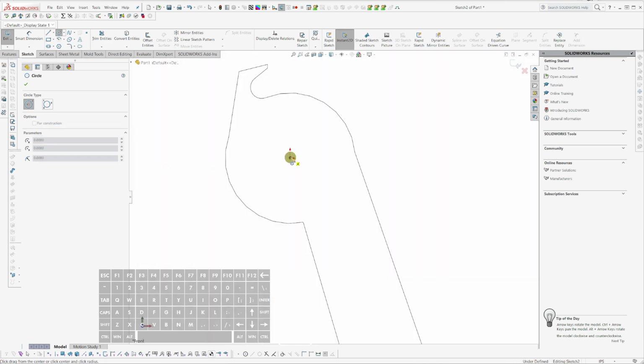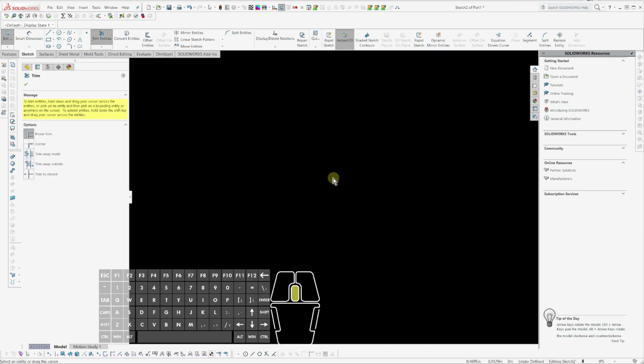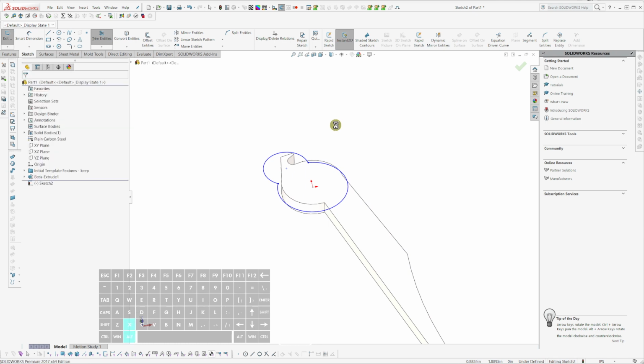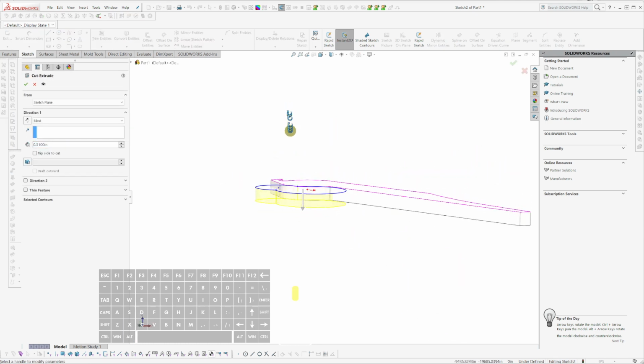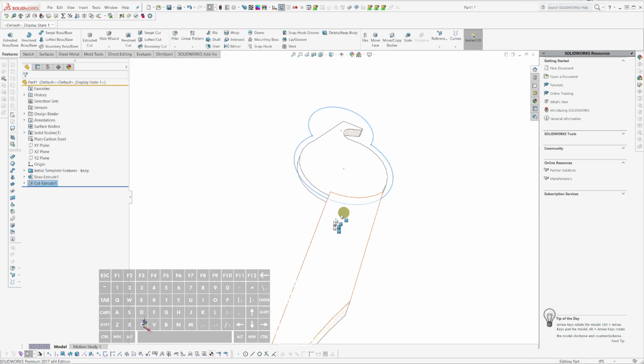And circle will do. Be a couple circles. Trim. And I am going to cut this away, like so. But I also need to go back this direction. Just a tiny gap. I'm going to say, I want 20 thousandths gap, so I want to say 10 thousandths. Because it's going to effectively sort of mirror. It's going to be a circular pattern. There'd be opposite hand feature. I feel like going the other direction, not that it really matters, but just for the sake of visibility.